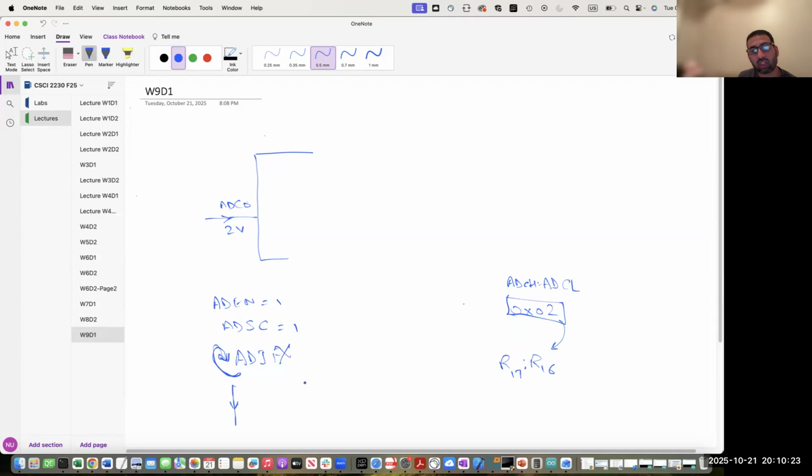I'm not going to do this. This is known as polling. So I am not polling my interrupt flag, and I'm enabling interrupts, which means that whenever this conversion is completed, give me a signal, right? Just enable the interrupt. And then what happens is that when the interrupt arrives, in the memory there is a specific location,